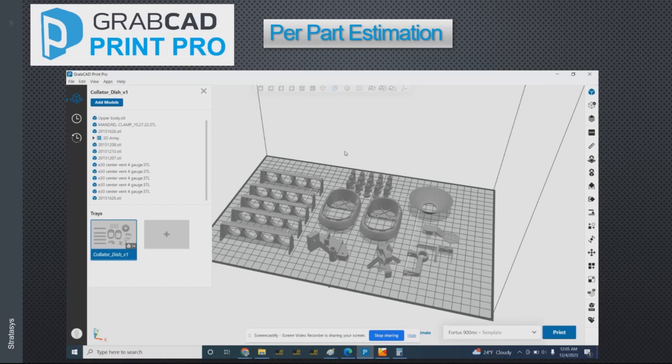Being able to do all of these at once. So let's say that I have this tray of parts here that's for either different departments and I need to allocate the cost to them, or if I'm a service bureau, I'm quoting these parts to different customers. On this left side here, we have 5 of these parts. In the back here, I have this array created of 15 parts. And that's important because since I created these as an array, GrabCAD will treat these 15 parts in the back as one when it does the estimate.